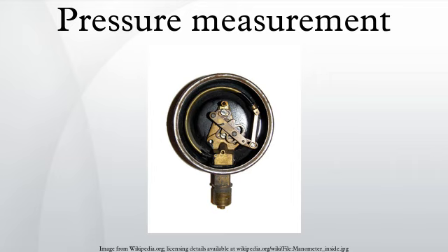made relative to ambient air pressure. In other cases measurements are made relative to a vacuum or to some other specific reference. When distinguishing between these zero references, the following terms are used. Absolute pressure is zero referenced against a perfect vacuum, so it is equal to gauge pressure plus atmospheric pressure. Gauge pressure is zero referenced against ambient air pressure, so it is equal to absolute pressure minus atmospheric pressure.